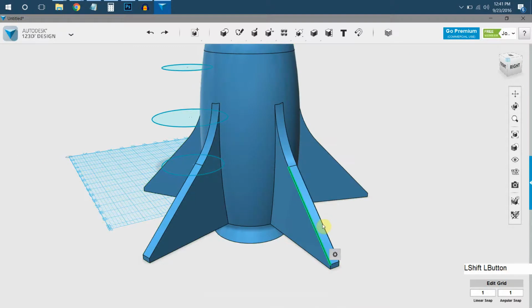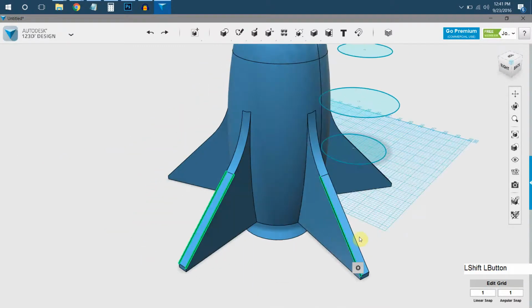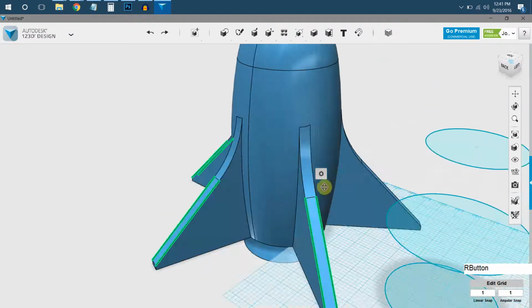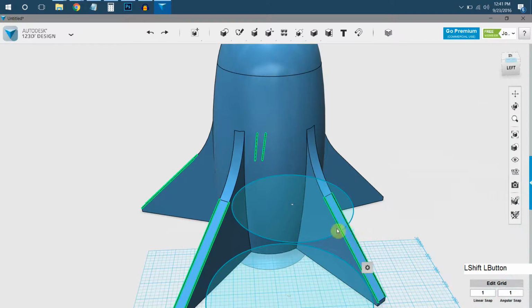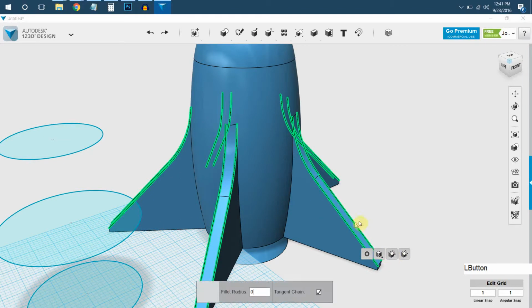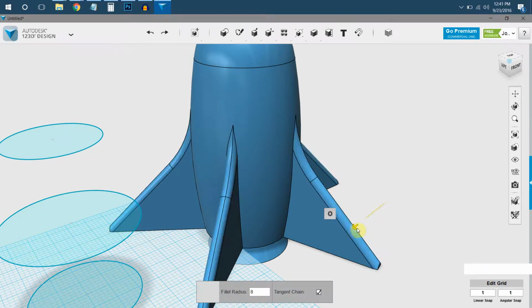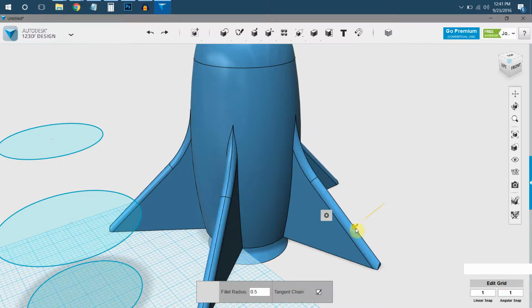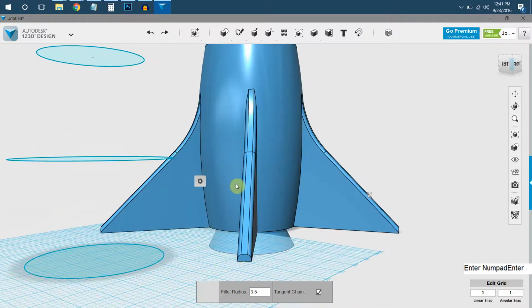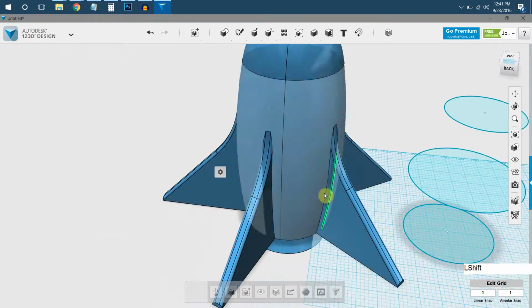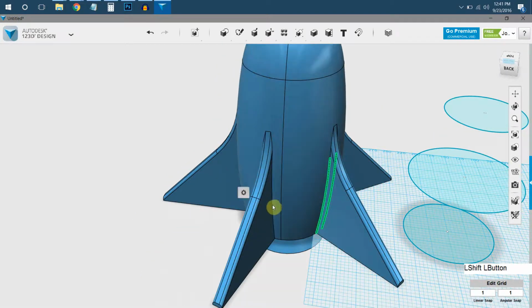But if I fillet, let me do this again. I'll select the top edges. Go to the fillet tool, and I'll fillet these. Oops, not too much. Just enough to make it look smooth, but not enough to blow out the top face there. Hit accept. Now, if I go to fillet the side edges, select all of them.